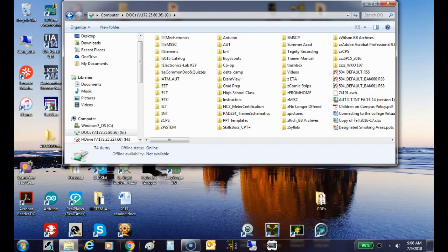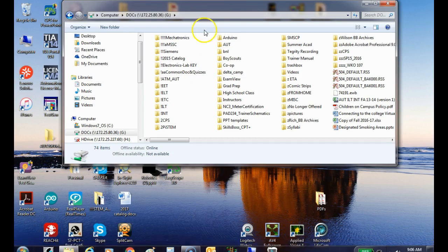So with all these sensors, over there we got photoelectric sensors. We looked at those. We got ultrasonic sensors. We look at those. We got position sensors. We got proximity sensors. There is a difference between a position sensor and a proximity sensor. A proximity sensor is a sensor that senses when an object is at a location. A position sensor knows where it's at within a range. Everybody understand that? So that's a big difference on those.